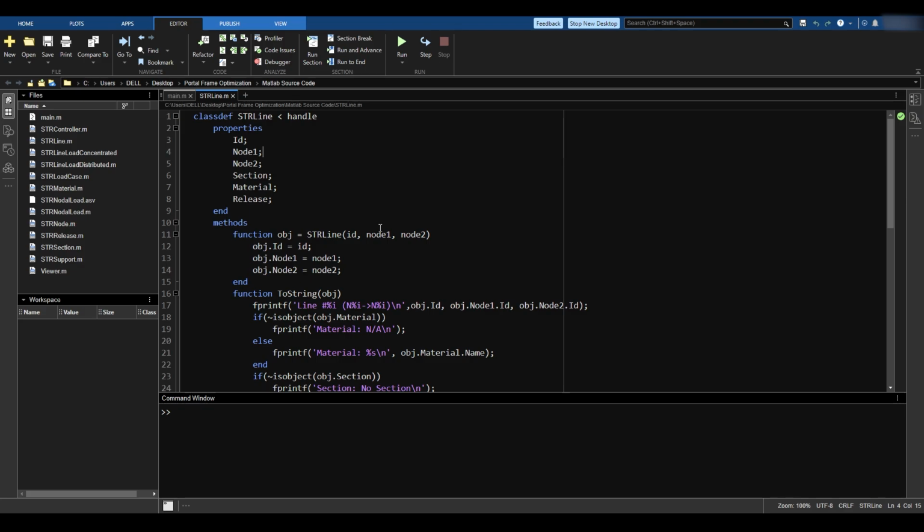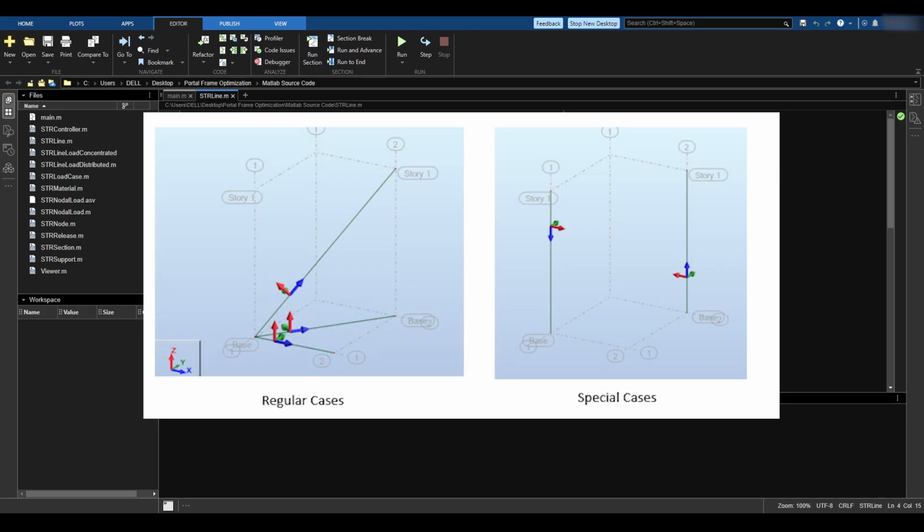Now, I talked about the local axis before in one of my videos in the finite element method series. We need to find the vectors by assuming how the vectors are. Let me explain exactly how my local axis is going to be for the member. The local x-axis is going to be the unit vector that connects the starting point of the element to the ending point of the element.